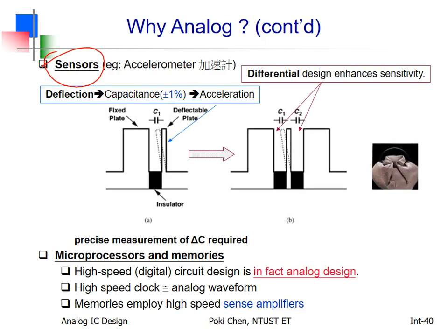How does it know your face? They have some kind of light sensor. It emits some light, reflected back to the receiver. If it is closer, then the receiver will get higher brightness, higher response. Then over some threshold, the smartphone will turn off the screen to help you save some power.